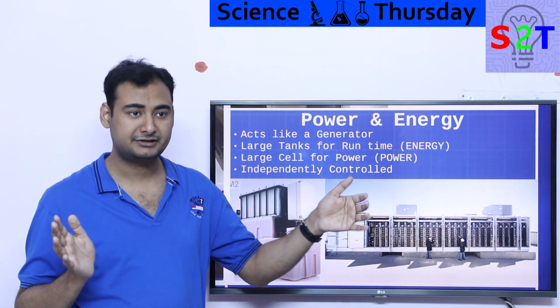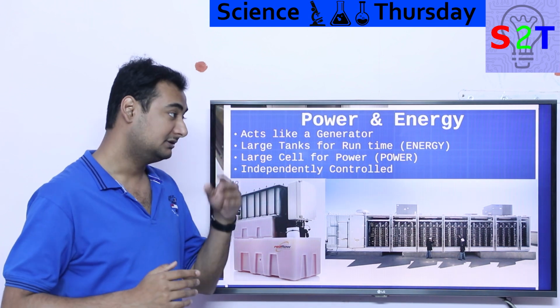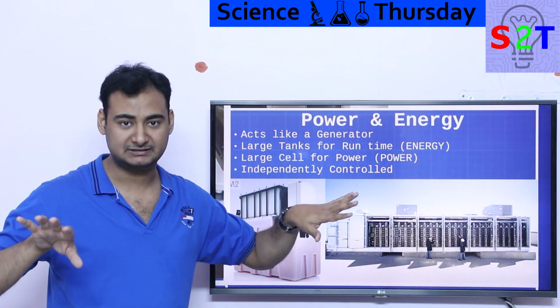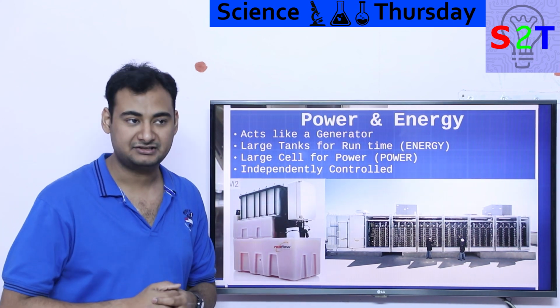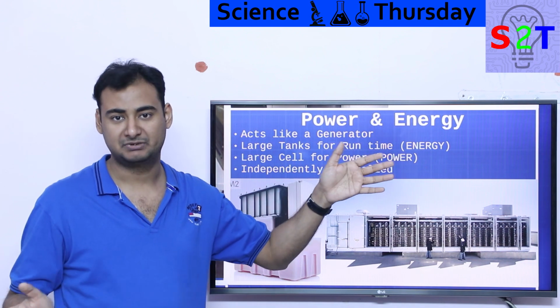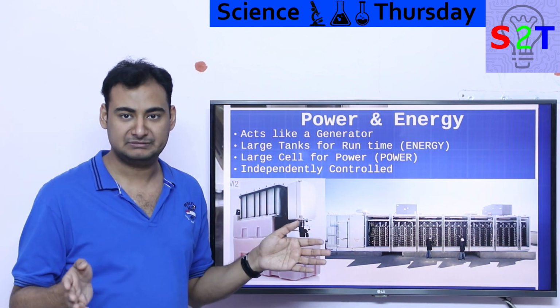Reality is same as a generator. You can have a giant generator or a small generator. You can have a giant fuel tank or a small fuel tank. That's all. In this battery, the unique ability is that both of them are separate components. So if you need a battery designed for some heavy application, you're going to have very large membranes, which are the main power component. You're going to have huge membranes, like hundreds of square meters of membranes.